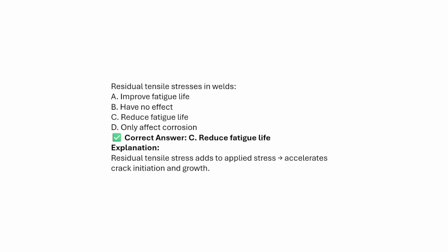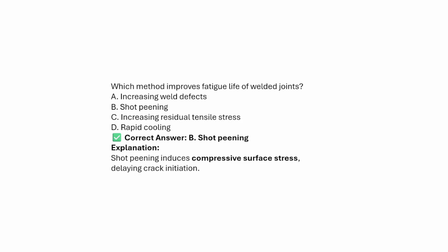The residual tensile stresses in welds: option A, improve the fatigue life; have no effect; reduce the fatigue life; or only affect the corrosion. Answer will be reduces the fatigue life. Reason: residual tensile stresses add to the applied stresses, which accelerates the crack initiation and growth.